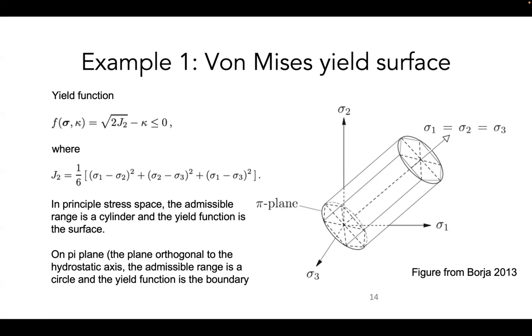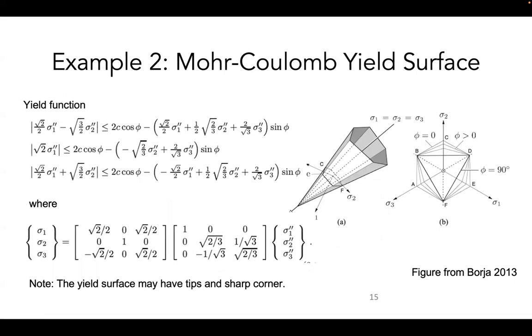The difference is that when you compute a gradient, you will have a different kind of complexity. I just want to mention that we cannot, in general, expect the yield surface to be smooth, and the non-smoothness of the yield surface could be a big problem. This is the Tresca yield surface, and one thing you can see is that you cannot write the yield surface within one equation.